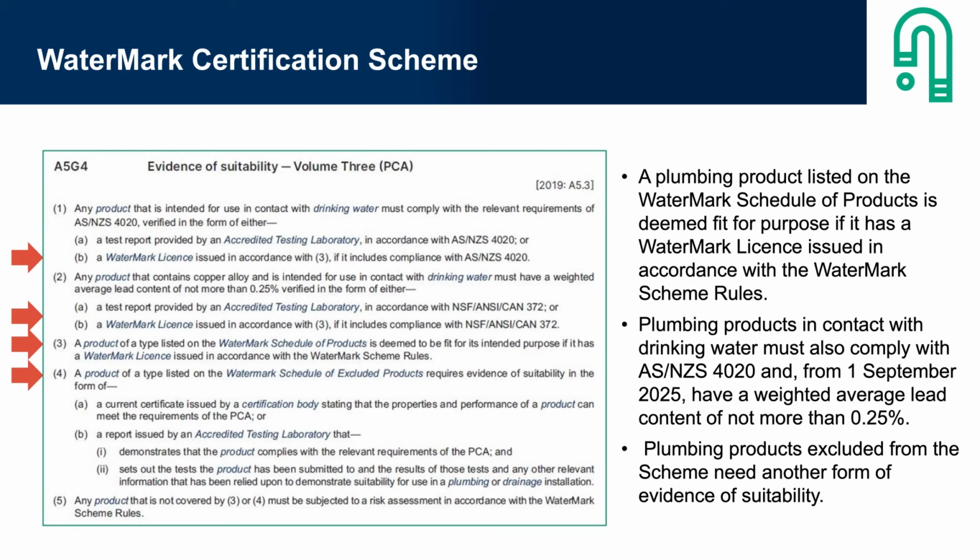If a product is in contact with drinking water, then it must also comply with AS 4020, testing for products in contact with drinking water. When the product is also required to be WaterMark certified, compliance with AS 4020 is included with the WaterMark certification.